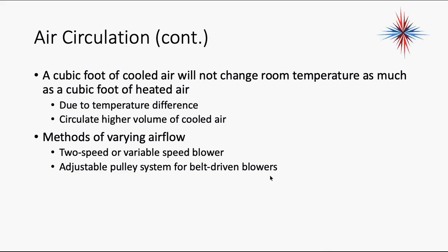Now, I don't know if any of you live in a house that originally didn't have air conditioning. Very frequent in the Northeast and the northern part of the country. The heating systems had much smaller ductwork. If we add air conditioning to a system that was designed for heating, you cannot circulate enough air.